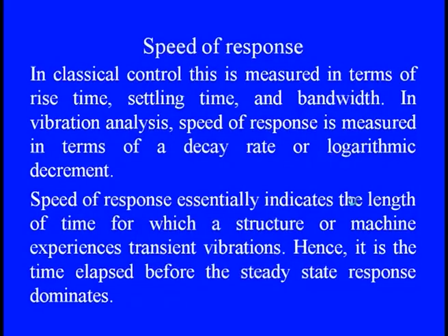When we are interested in locating the speed of response, in classical control theory it is measured in terms of the rise time, which is generally how long the response takes before coming to the steady state, or even the settling time or the bandwidth. In vibration analysis, the speed of response is measured in terms of the decay rate or the logarithmic decrement. This is the analogy between classical control theory and vibration analysis.